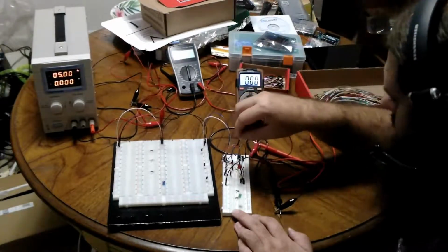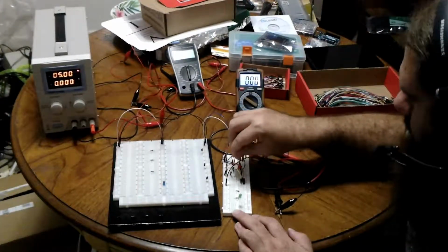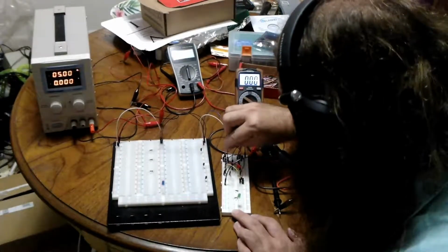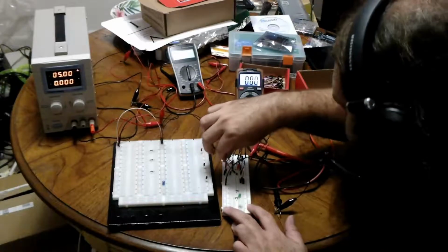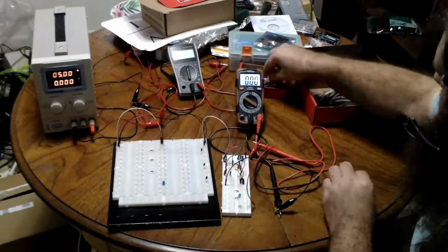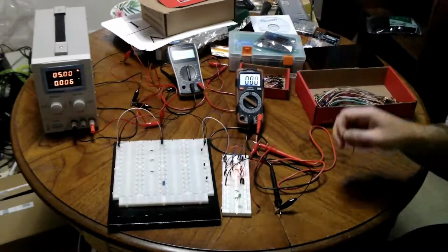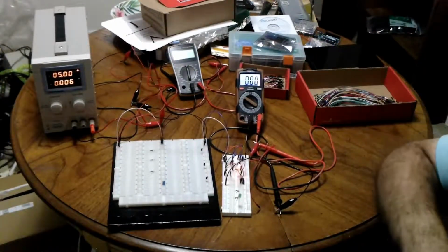So now measure over at the start of the LED, and we get nothing. How about the start of the resistor? And we get nothing. How about the start of the first resistor? And we get something. So now we decide this wire may be bad. So let's put in a different wire. Let's use this wire. And all of a sudden we have an LED. So this wire now goes in the trash bin. That's what you've got to do.